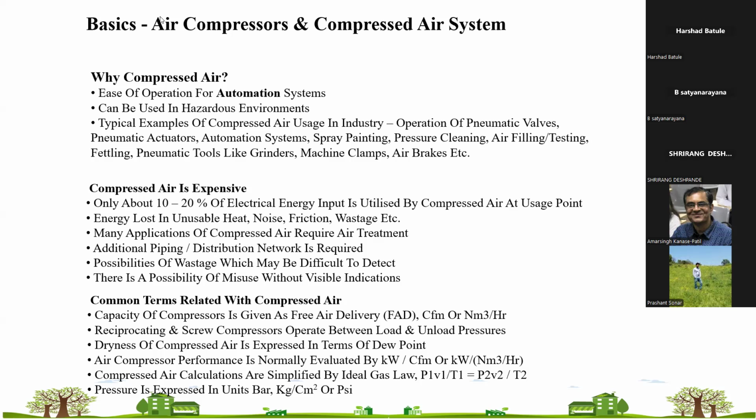All of that accounts for 70 to 80% of energy. So if you are applying 100, you will get 10 to 20. That's why compressed air is the costliest utility, we can say. It is widely used, but it is also an expensive equipment.